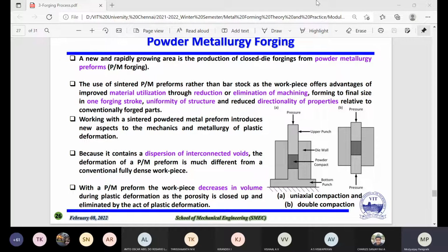But if you have a small crack, then better, and this is cheap, because it depends upon the price also. A lot of tests are there. Probably, I think we have studied 8 or 9 tests, such as ultrasonic or something, but we are normally going the cheaper way, the dye penetrant. There is a liquid dye that is put on the surface. After some time you will see the dye color going inside, and the moment it goes inside, you will find the crack.